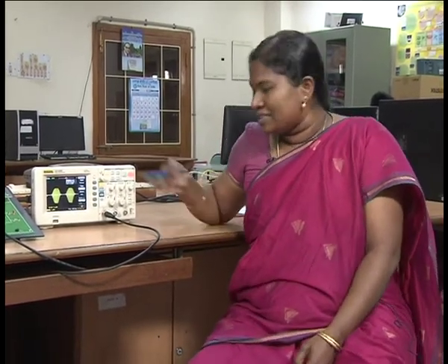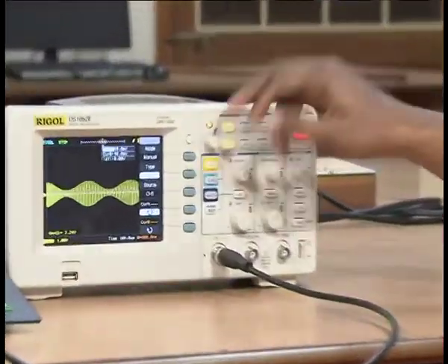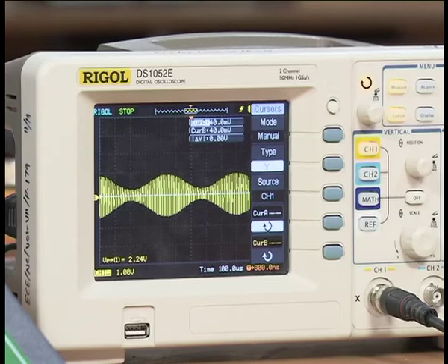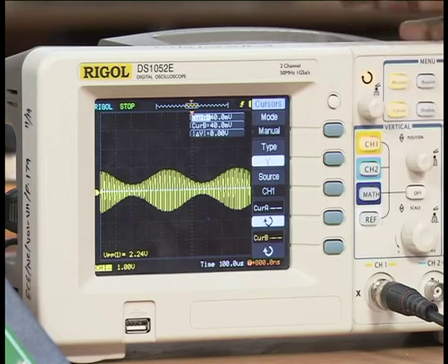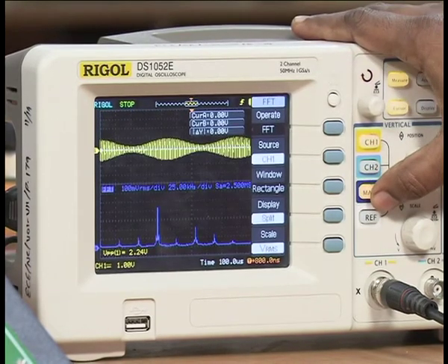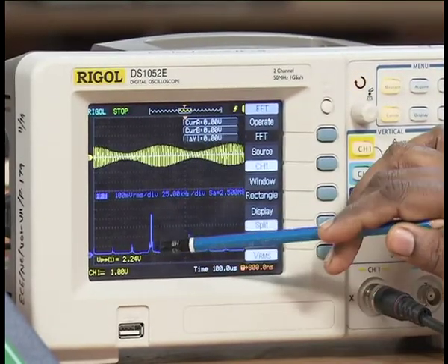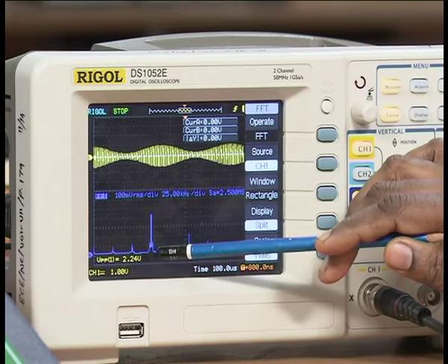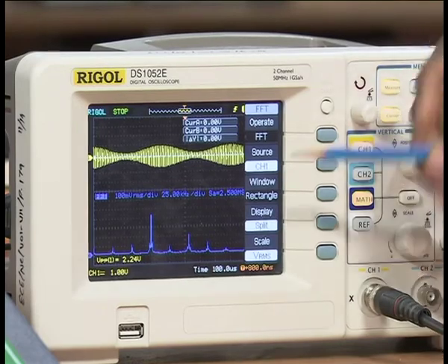Similarly, we can see the frequency of operation of the AM modulated waveform. I just set back to mu less than 1 and we will see how to measure the frequency of operation. Now, it is a modulation index less than 1. DSOs have the facility of viewing frequencies: you can go to the math operation and click FFT. Now we can see the frequency response of the AM modulated wave, where you can see the center carrier frequency followed by FC plus FM and FC minus FM.